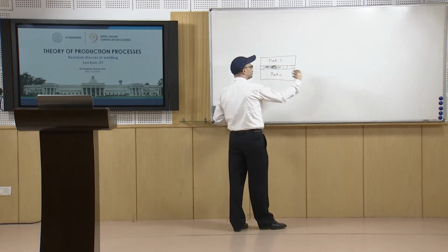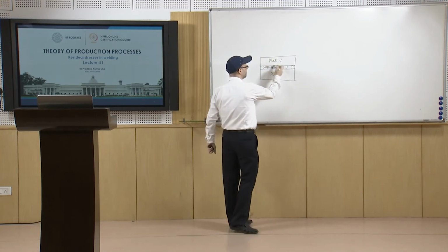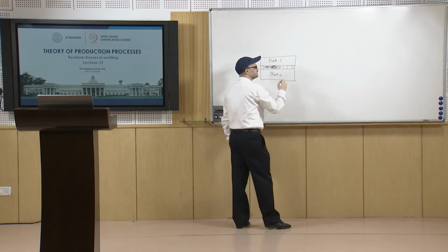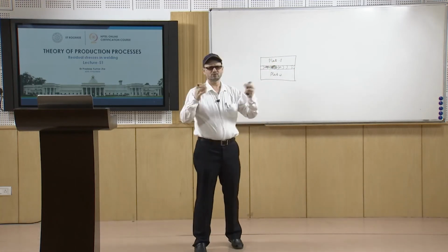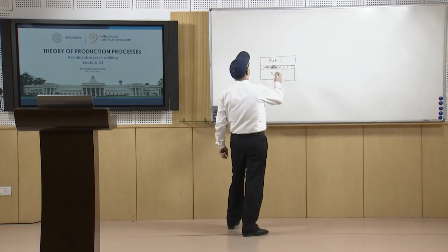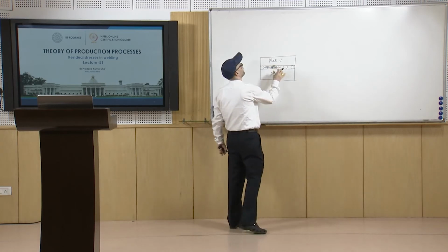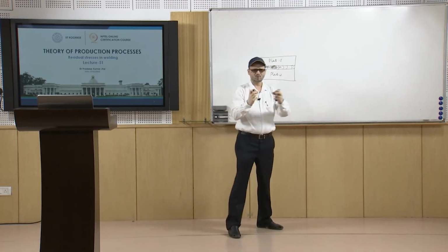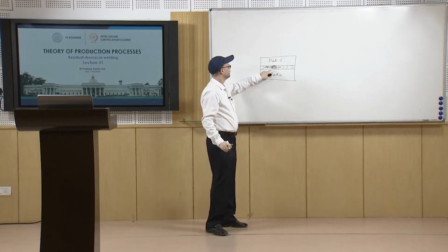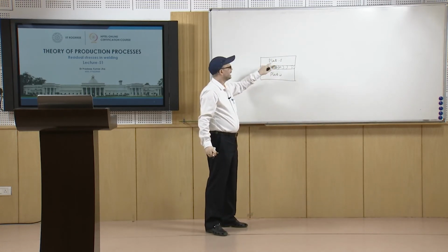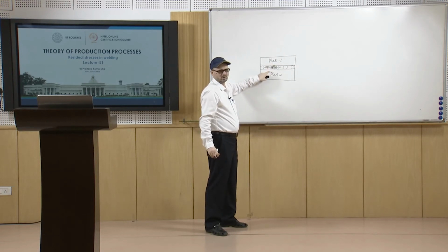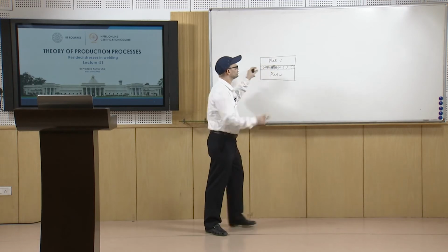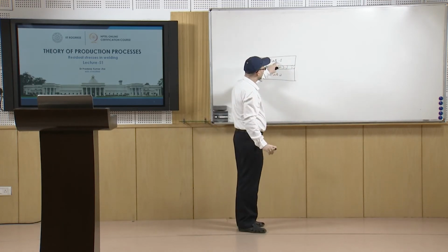Now, this is during the heating stage. When it is cooling, the trend is opposite. When you are cooling, this will be trying to contract, because the temperature falls very rapidly, and the other portions are still at high temperature, heated. It tries to contract, and the heated portion will try to oppose it.